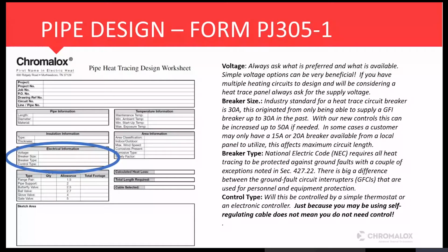Control type, it's pretty self-explanatory. We're going to do it with a simple thermostat or an electronic controller. And just remember, just because we hear it every day, just because you may be using self-regulating cable does not mean you do not need control. So just keep that in mind. We always want to include control.